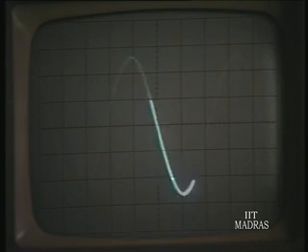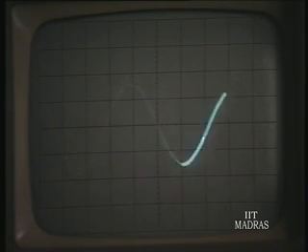Now, show them only the AM detected output, switch to single channel, yeah. So, this is the AM detected output, okay, that is better. Okay, she is changing the depth of modulation now, right, decreasing, increase it, yes, okay, leave it at that, change the frequency, yes, the modulating frequency is changed, right, you can see, change the depth now with the highest frequency, yes.